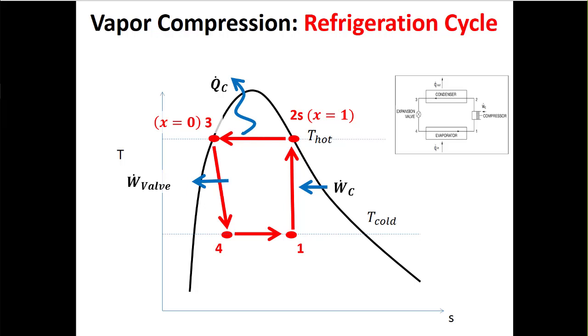We're going to say for now that we're producing power in the expansion valve, that it looks kind of like a turbine. We're at least going to approach the first law that way. And then we're going to add heat at the evaporator. Right, so I got 4 processes. My heat exchangers here, I'm interested in heat transfer rates. And my power terms are going to be at the compressor and the expansion valve.